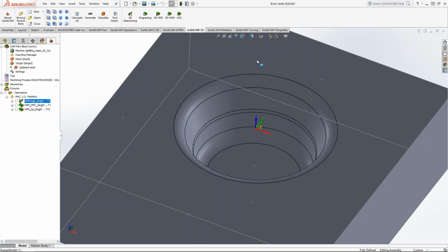Okay. Now, how about coating? Were you running mainly TiN? Yeah, mainly AlTiN, aluminum titanium nitride. Those seem to be the harder coating and the best wear. Most of this material I ran dry with just an air blast to keep the chips out of the way, keep from recutting the chips.